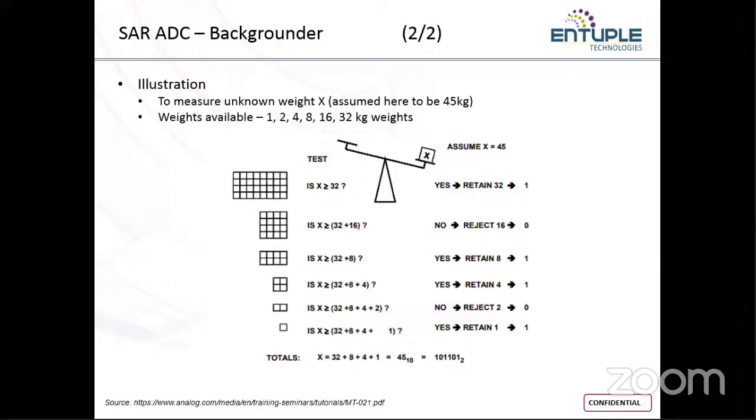If the value of voltage sent from the successive approximation register is less, then the bit will still remain at 1, and the next significant bit will be set to 1. And if it is greater, then the MSB will be set to 0, and the next significant bit will be set to 1. Again it will go to compare. This will be happening until all the 4 bits get filled up. This is the principle.